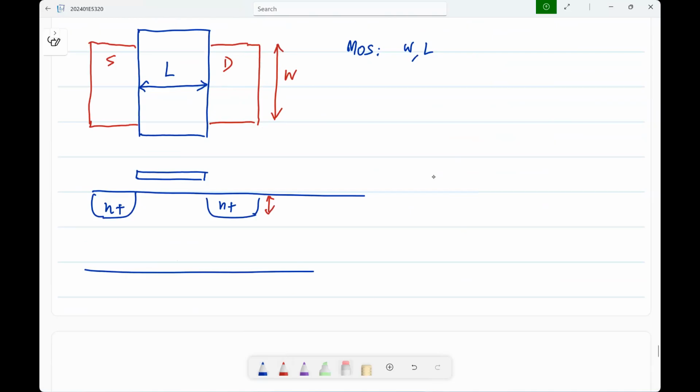and also any component comes with a bunch of other extra components. We already saw that. That is, you have a MOS transistor, but you don't get only the MOS transistor. You get those diodes, right? You will get these diodes. Now, of course, you keep them off by making sure that the substrate potential is the lowest in the circuit. But even when they're off, they will be contributing capacitance. Okay. That is, when the diode is off, basically the depletion region is like some insulating layer, and then you have the depletion capacitance of the diodes.